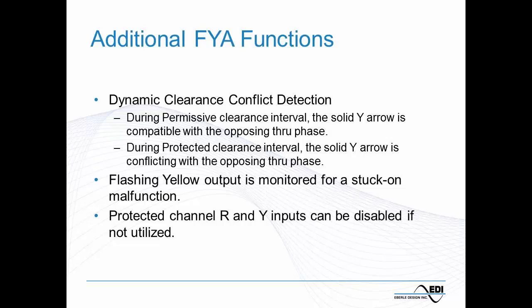I mentioned earlier that on our protected green load switch channel, we have red and yellow outputs that typically will not have signal heads connected to them. So we know that in a NEMA cabinet, if there's no load on a load switch output, the monitor will sense that input as being active all the time. So historically, we would have to add a dummy load resistor or some kind of load to the cabinet wiring. We'd rather not have to do that. So if we're not using those red and yellow outputs, we can program the MMU to ignore them and force them to the off state.